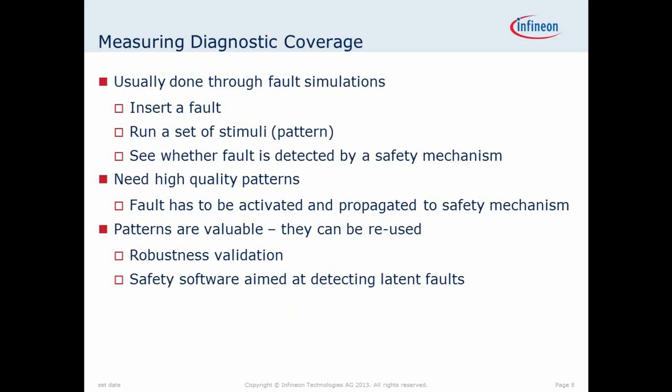So you need to demonstrate a diagnostic coverage. Typically, how do you do this? Well, the standard way to do this is through fault simulations. You just insert a fault, you run a set of stimuli, and you see whether the fault is detected by a safety mechanism.